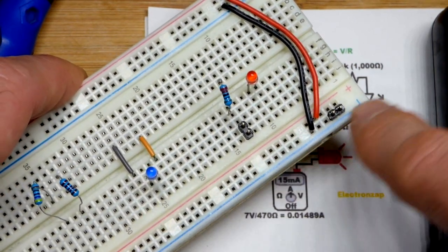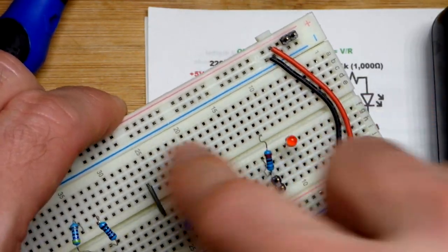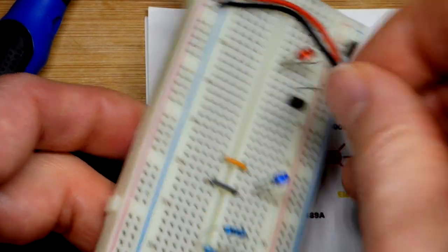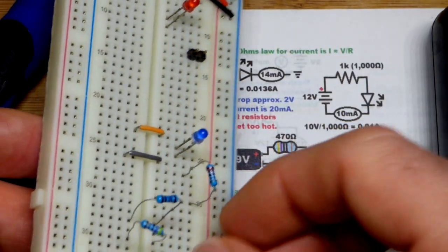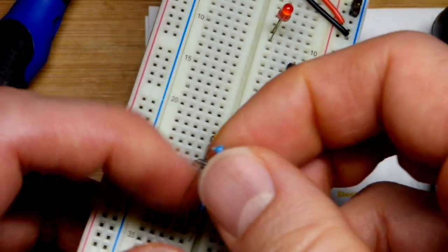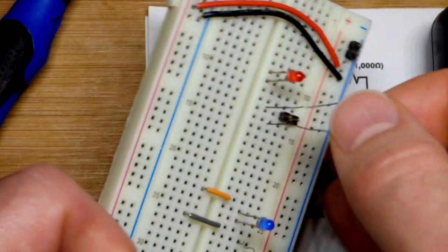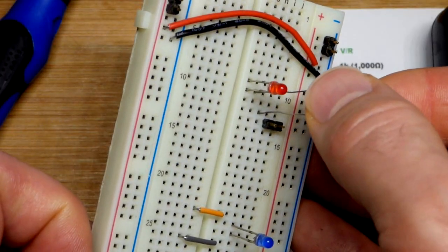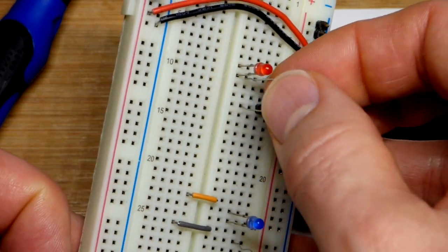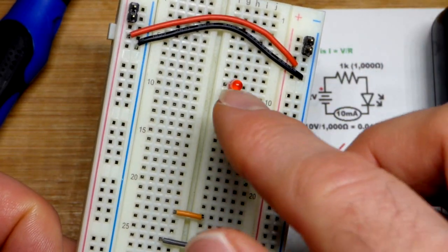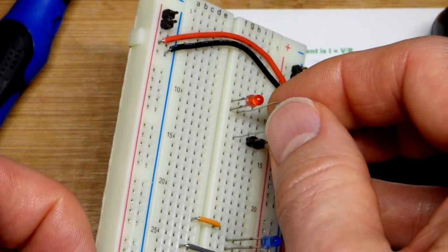It'll power all of these holes next to the blue line right there, as well as over there. So we will take away the 220 ohm resistor, and now we'll look at 9 volts, 470 ohms. So there's the 470 ohm resistor. Yellow and violet for 4.7 are very commonly used values, and then whether it's 47, 470, which this is, or 4,700 and so on, is determined by the multiplier color of the bands. So be aware of that.